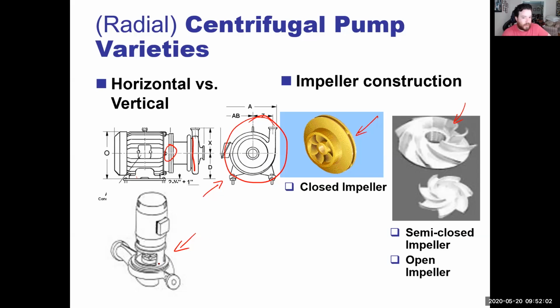It's fine when you go into it thinking it's one thing and then find out it's a lot worse. But taking it apart just for discovery is not a good way of doing shipboard engineering. You want to exhaust all efforts of investigating while the pump can still operate, if it's the only one you have.